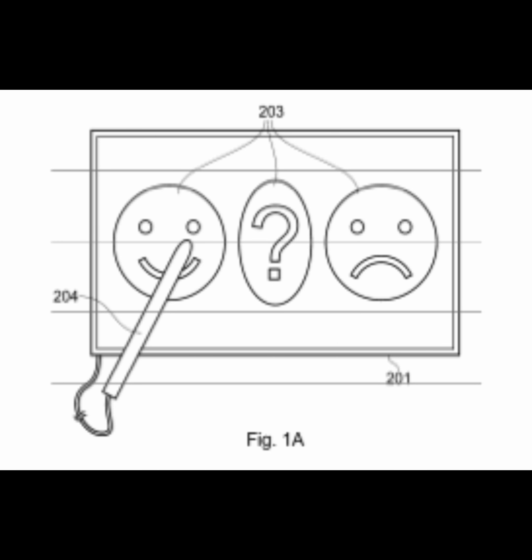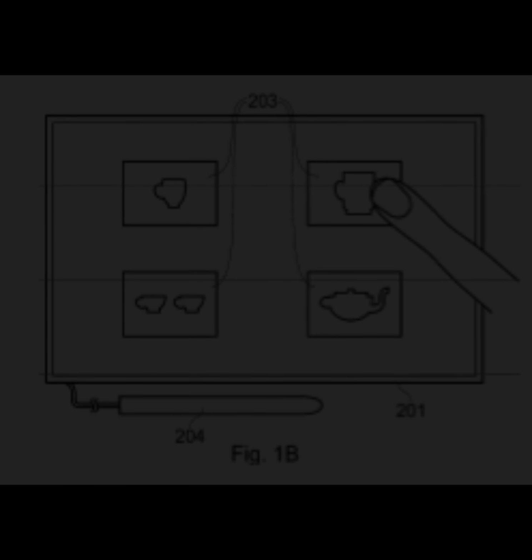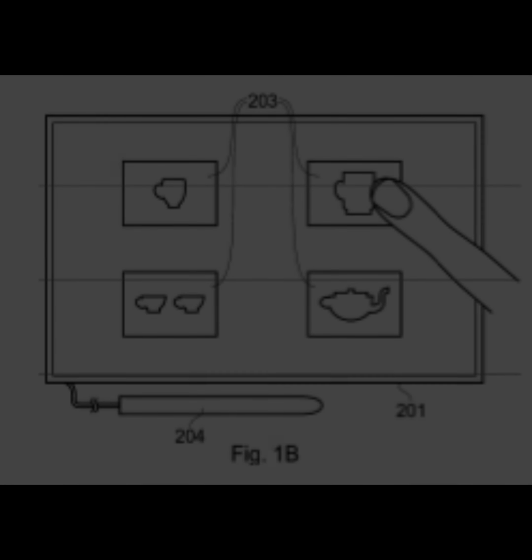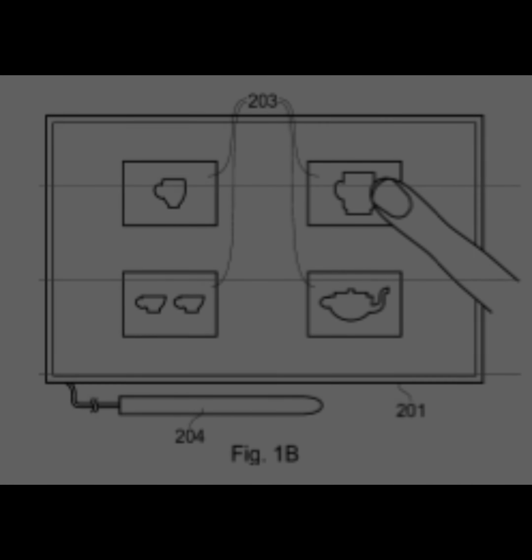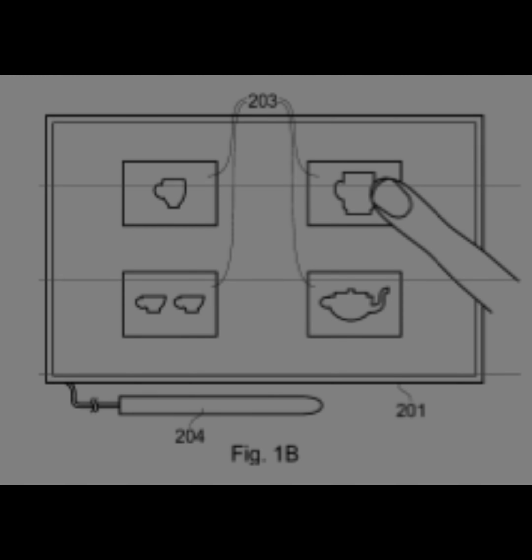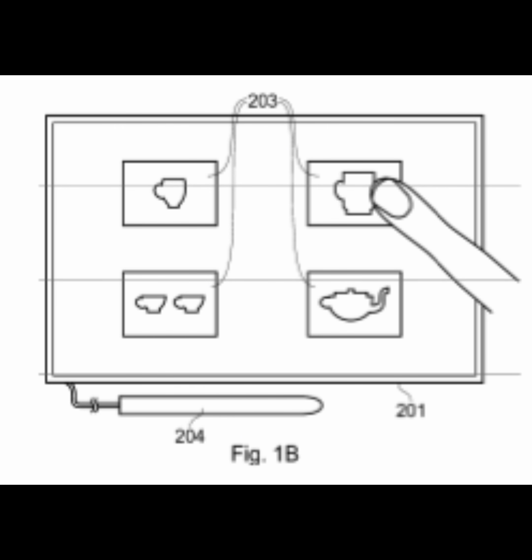When the stick or a finger is pressed against the panel so that the resistive layer 206 is brought into contact with the conductive layer 208, the conductive layer 208 picks 2 voltages off the resistive layer 206 in 2 consecutive time periods. The combination of a first voltage in time period T1 and a second voltage in time period T2 characterizes the contact area between the resistive layer 206 and the conductive layer 208, and therefore also the area of the panel on which pressure is exerted. Time periods T1 and T2 of 0.25 seconds have proven to be long enough to reliably detect whether pressure is exerted in this area.